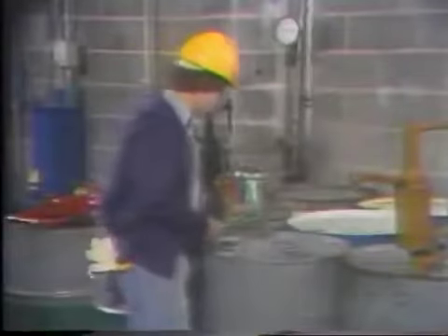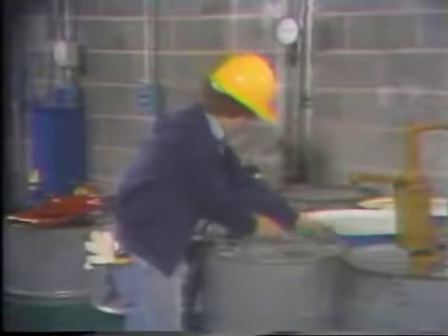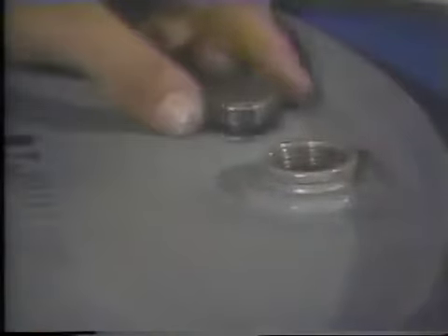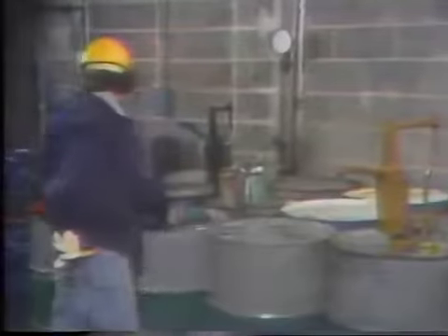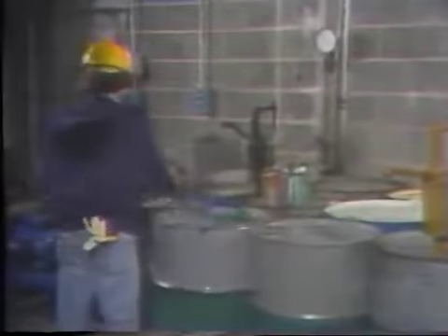For the pump to operate properly, the barrel usually needs to be vented. This is done by removing the small vent cap on the top of the barrel, as you see here. Another job that must be done is cleaning the barrel pump. These pumps can sit around for a while and dirt may collect on them.